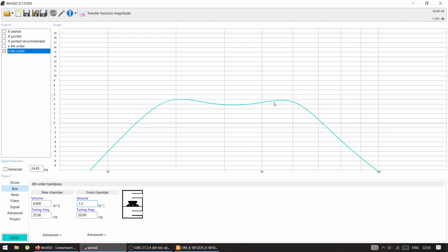So this is a typical 6th order response. You have 4th order, which is like one mountain, and with the 6th you have a broader, bigger bandwidth, so it plays higher. But if you stretch it too much, if you want your 6th order to play too wide of a range, it's gonna have a dip in the middle. See, it's going down, and you have these, they're called dog ears. And that's the beauty of it. You can play with it and have different variations.